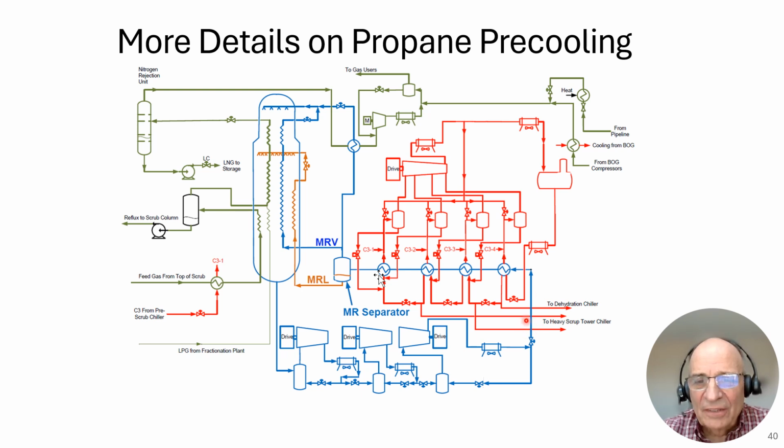Here, you get a JT valve. You have liquid coming into the chiller, and the chiller is a vessel that has vapor on the top and liquid on the bottom. So the vapor goes up the top and the liquid goes on to the next JT valve. And then again, the vapor is separated, vapor goes up the top, liquid goes to the next JT valve, and so on, until you get to the final JT valve, and it becomes all vapor that is then fed up to your suction drum. And the MR goes through three stages of MR treatment.